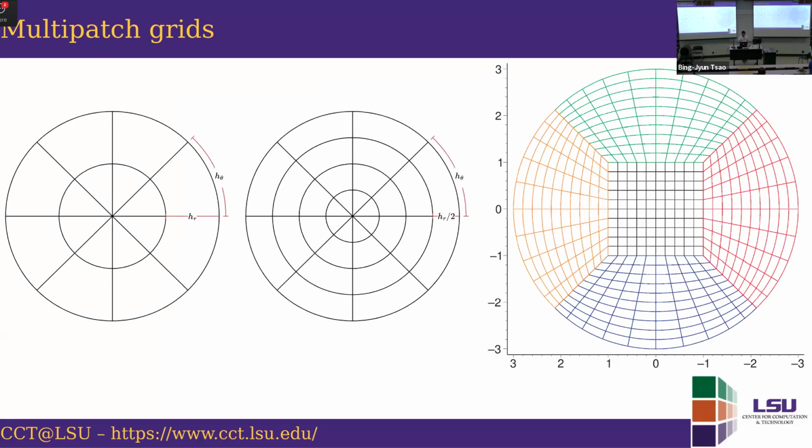And for that kind of thing, the smartest thing to do would be to use a spherical or spherical-like coordinate system, right? And this is basically because in this, you can decouple your radial and angular resolution. So usually what we want is a lot of radial resolution, but not so much angular resolution, right? Of course, the spherical coordinate system has a problem. It has a divergence at the origin, right? It is discontinuous at the poles, I'm sorry, right?